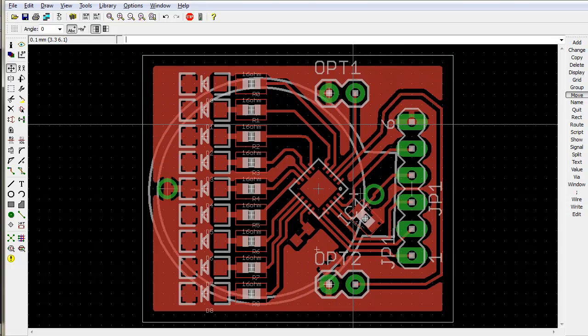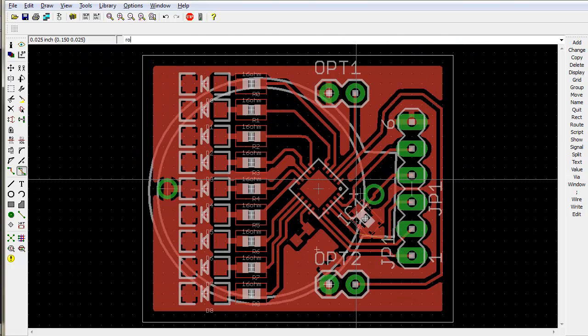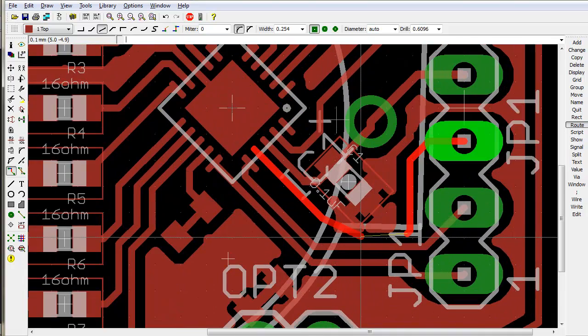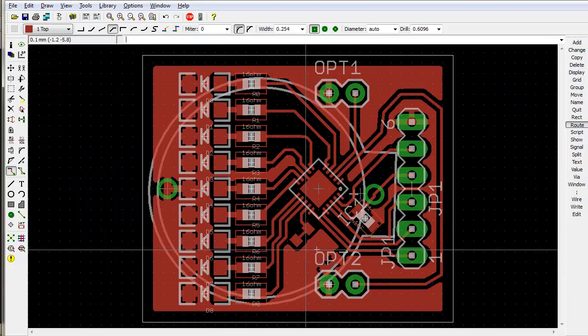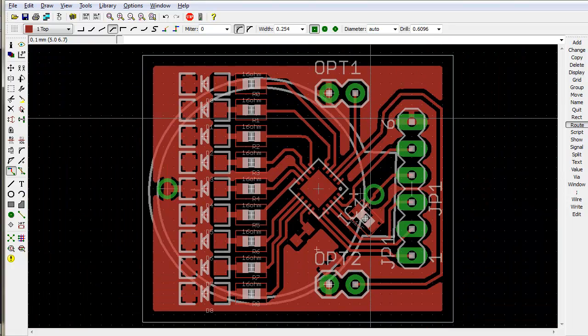So I actually made the borders slightly larger. There's a change I made to it somewhere along, but we've got kind of the basic gist of it now. Some of the routing is definitely a little bit weird, but what we can do is use the rip command, and the rip command removes individual parts if we use it carefully. You do it twice, use the RA, it will fill in. So now we can go in there, zoom into it, and what's this command? There we go. That's quite lovely. And we can just straighten out some of those rather nasty little bits. But there we go, that's basically the board routing without using the auto router.